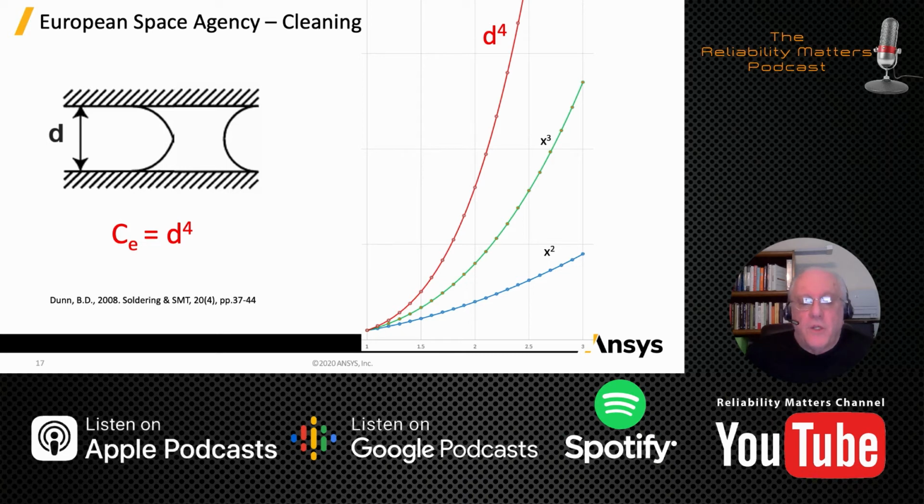So the implication of that is when you're designing your circuit boards and you're selecting your components, for cleaning purposes, you need to fight for every little micron that you can to get better and better spacing so that your cleaning effectiveness is enhanced instead of degraded.